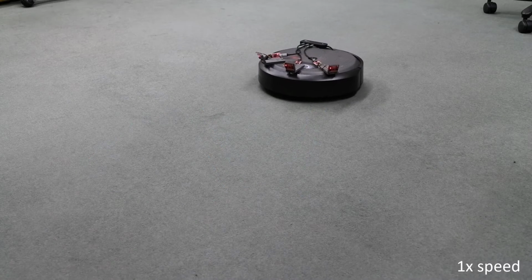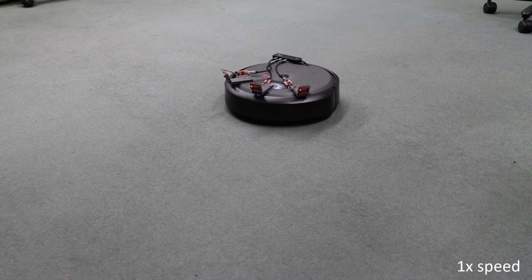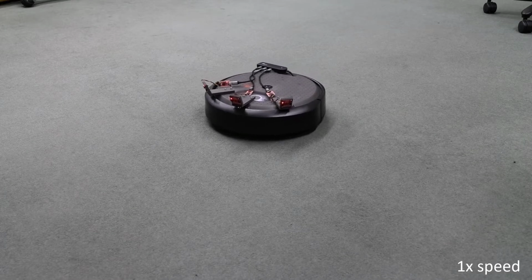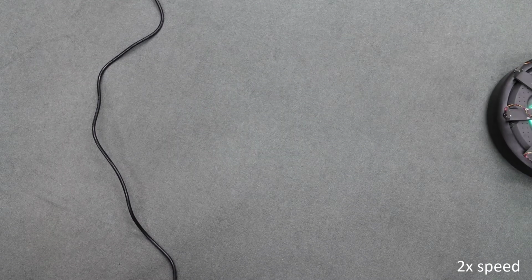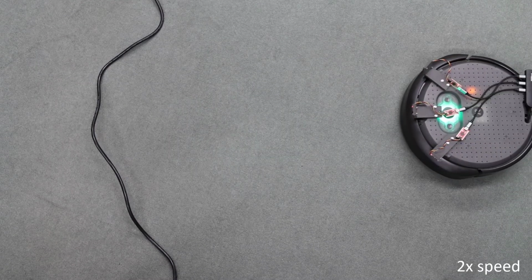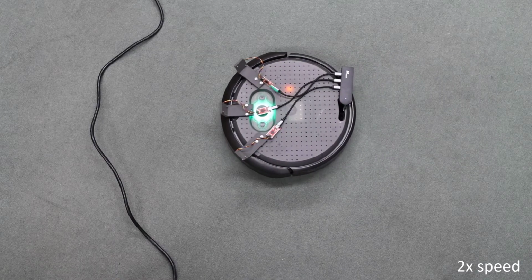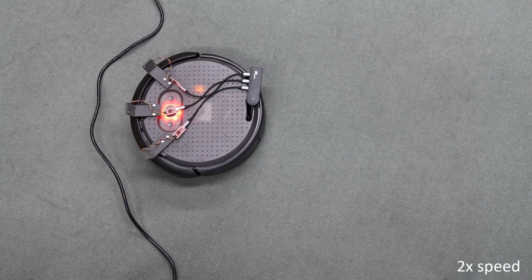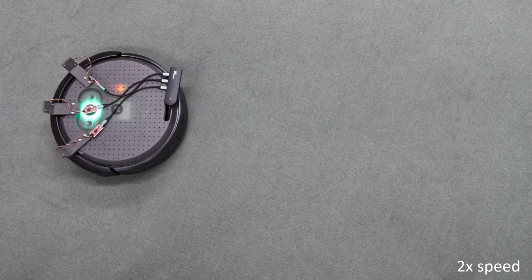The robot begins by driving in a straight line for 10 seconds to gather measurements of the empty planar surface from each of the 3 sensors. These measurements are used by our method to model the surface. After modeling the surface, the robot moves forward until it detects an obstacle. When the robot does not see an obstacle, the light on top of the robot is green. When an obstacle is detected, the light changes to red and the robot stops. If the obstacle is removed, the robot continues.